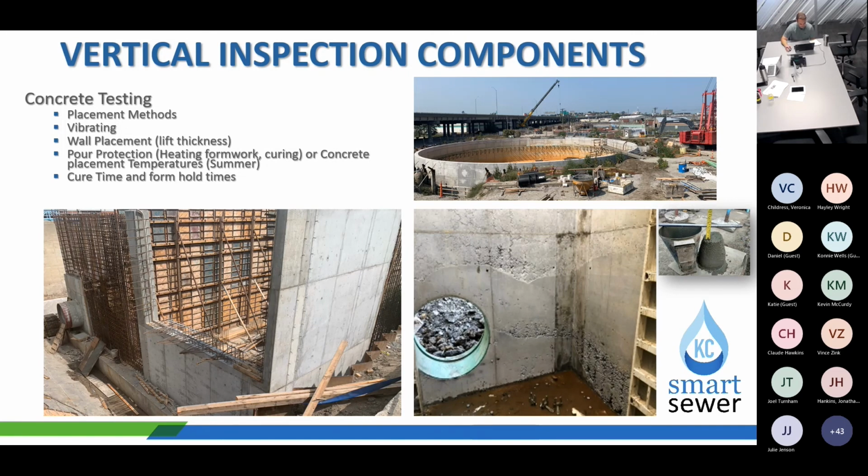If you look at the photos here, just as an example on the bottom right, that was a situation where the contractor was pouring some stuff, and the concrete wasn't ideal and the pour rate wasn't ideal, and we ended up with some pretty bad conditions after the pour was finished up. So understanding how all these things come together, so you can be aware of it as it's happening, or most preferably before things go in place, and you're talking with the contractors so that they're not getting ready and getting prepared to do things that aren't allowed is important.